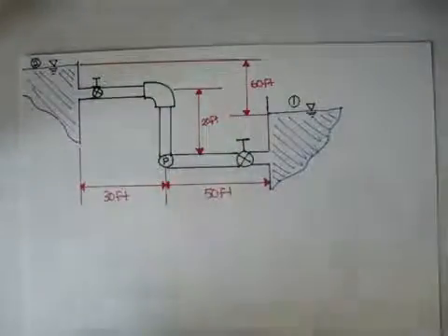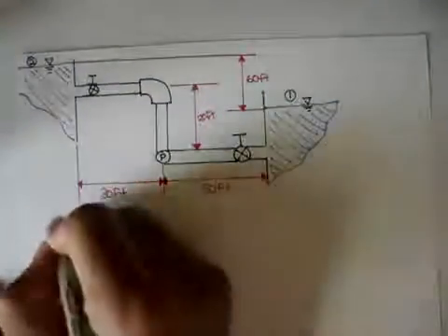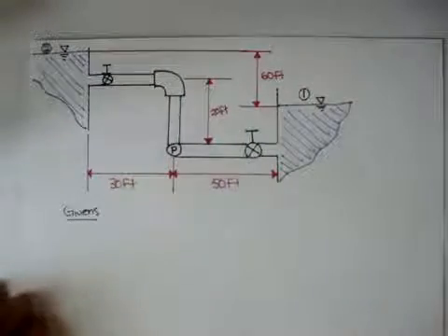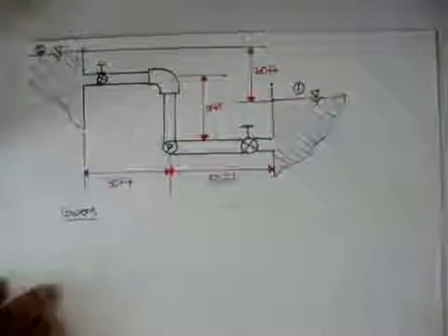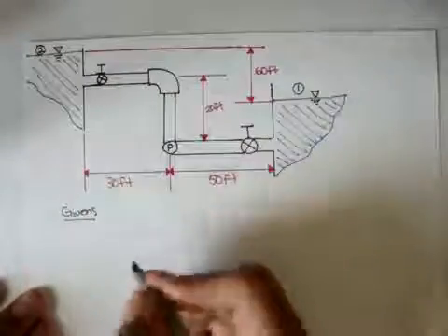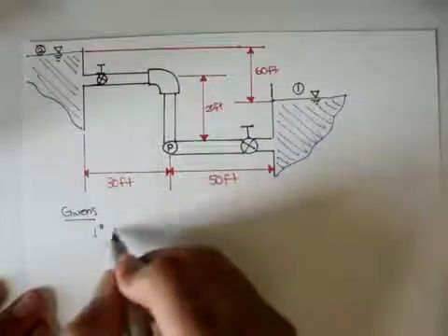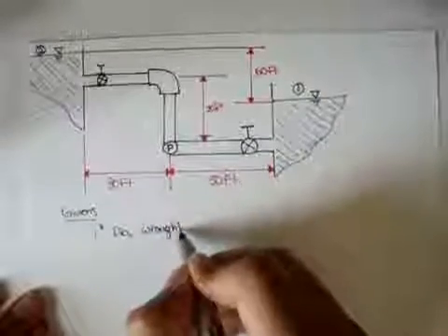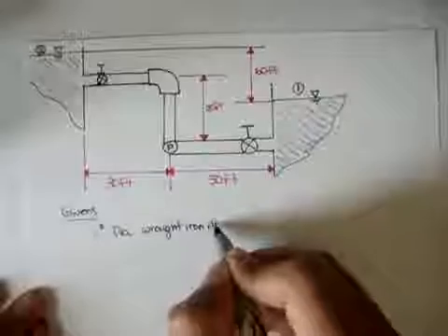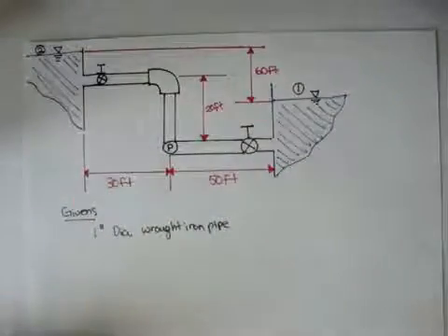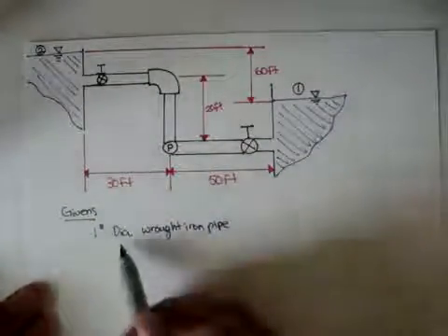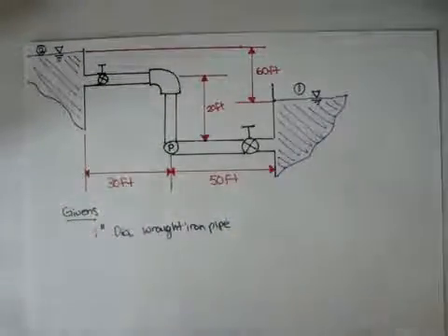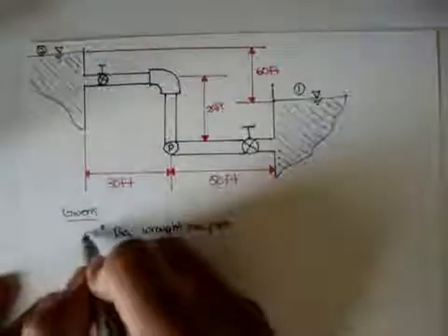Okay? And some of the givens. Let's write down the givens. These are givens in the problem. They're on my paper. The problem says that this pipe is a 1-inch diameter wrought iron pipe. And so they give you the material of this pipe, so immediately you should think that we should go to the relative roughness chart, and we will in a second. So that's the first given.